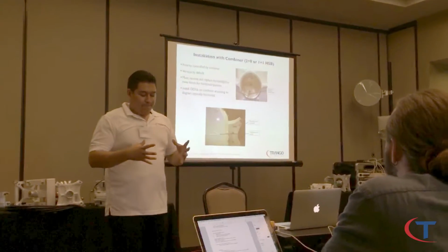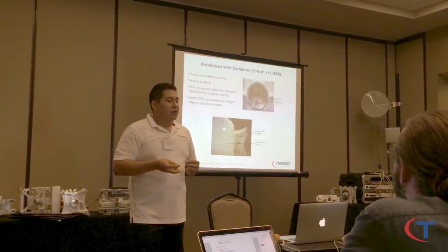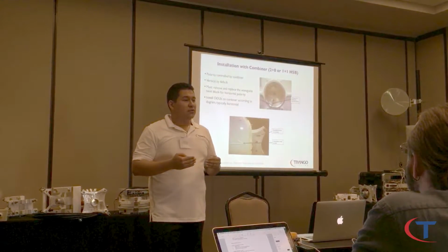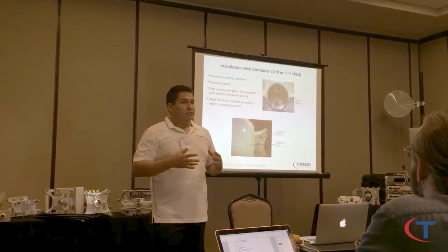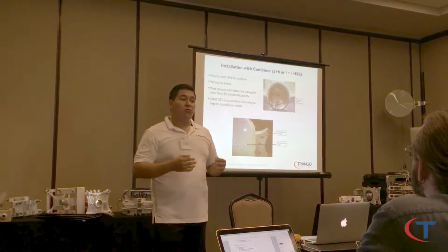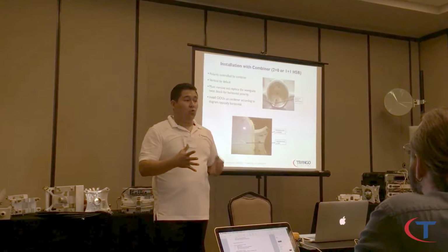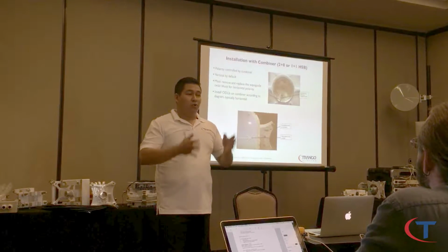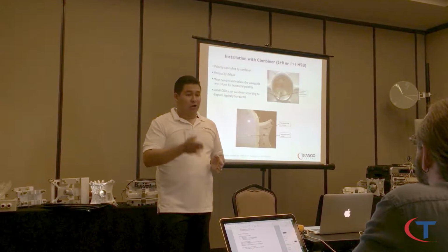Inside the combiner, you're going to have the waveguide orientation. It's going to be vertical on both sides, or it could be an orthomode combiner. Orthomode combiner is one side V, one side H. Standard mode combiner means both sides are the same polarity, vertical or horizontal.